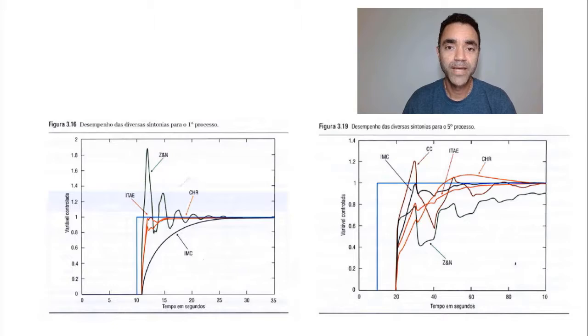In any case, these methods can be useful as a first approach to define the values to add in the PID controller. How easy that is depends on the process, because when we go to the field, we are not dealing with equations, Laplace transforms, or other kinds of differential equations, etc. We need to make changes in the controller, evaluate the process, and based on that define which are the best values for the PID.